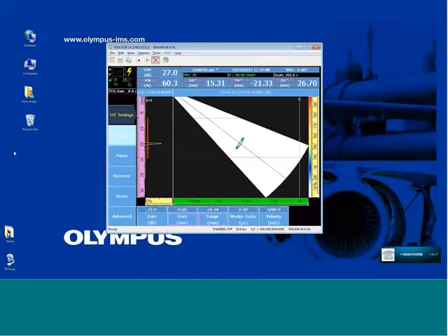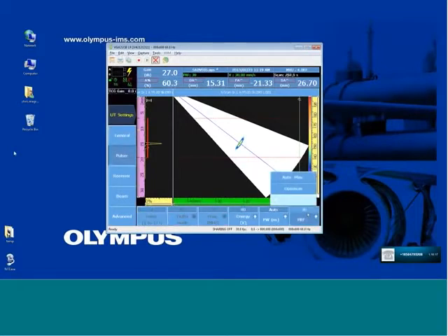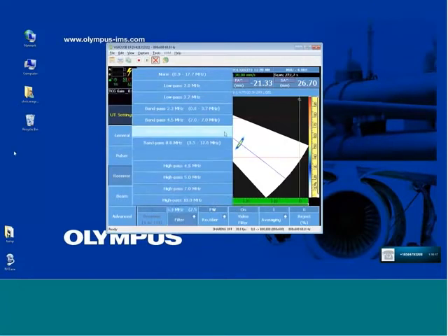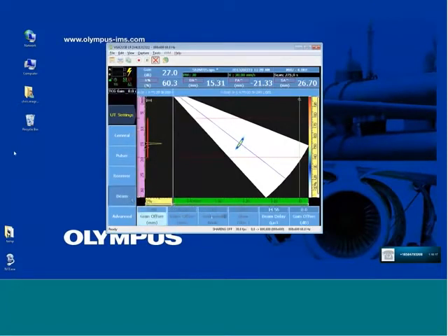The velocity was determined from the component during the wizard for carbon steel. Under our pulsar, we can normally just set it to optimum. Select one of 3 energies based on the pitch of the probe and best results. Select the filter. And our beam settings that you see here were generated by the phased array calculator.